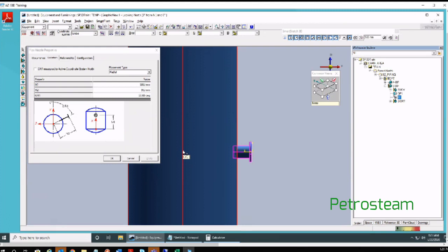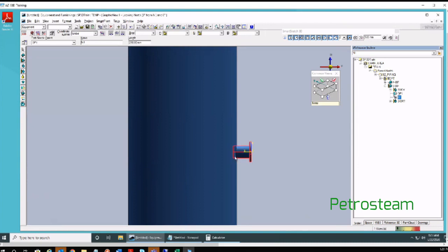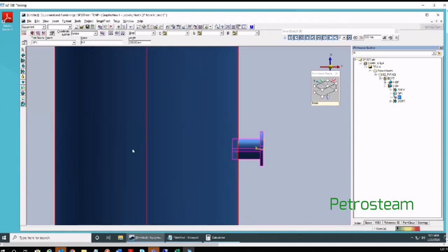Maybe to help that program, you are giving total length from the center. But here, you don't need that. As per me, you don't need that. Normally nozzles are welded on the equipment, correct? So in that case, giving the extra length is not at all required. For visualization purposes, you can give a little extra length to show. Outside it is 200 mm, but still I have taken 250 only to penetrate through this cylinder. You don't need to give up to the center.